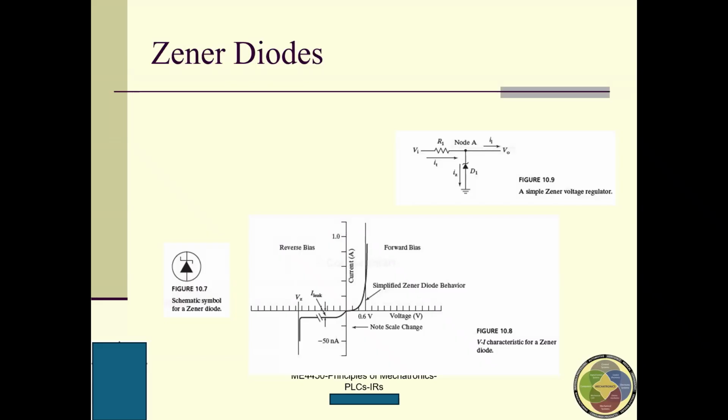Yeah, that's good. For this Zener, if we apply it in reverse bias, we will have a stable voltage. This is a very beautiful property. If you want to stabilize the voltage somewhere in your circuit, you can put a Zener diode there, and then you can see the voltage across the Zener diode will be almost constant. This is a very, very beautiful one.